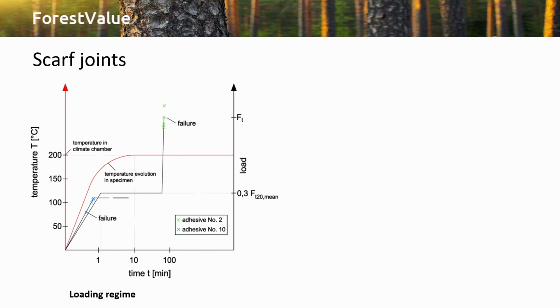And what is most important also in this test, we didn't load the specimen after they were heated, unloaded. We loaded the specimen within the heating, within the hot temperature regime, as you can see here. So we have a target temperature, which is maybe in this graph 200 degrees, and then the specimen is brought into that chamber, is loaded, and it takes about maximum 10 minutes that the specimen reaches the target temperature.